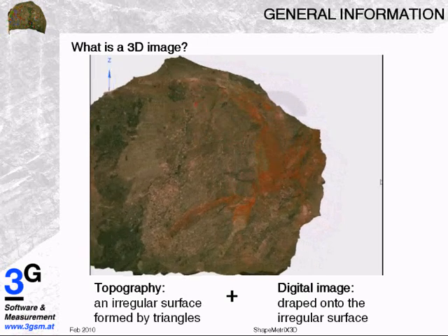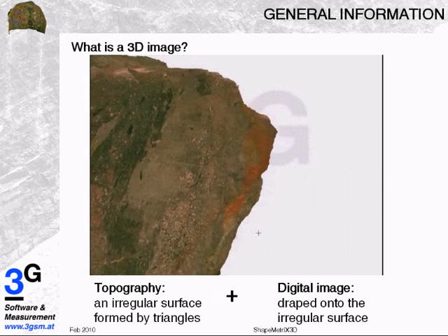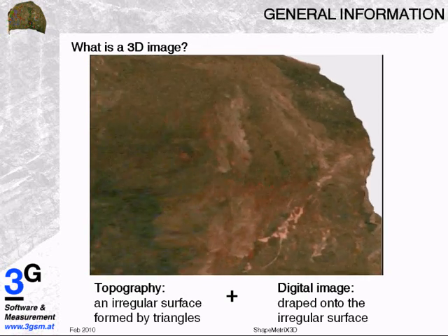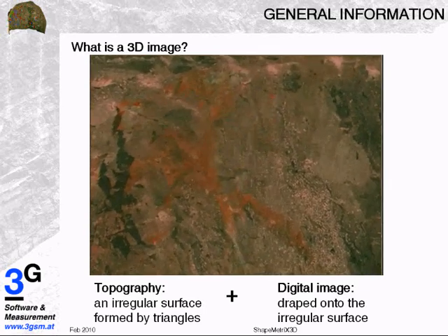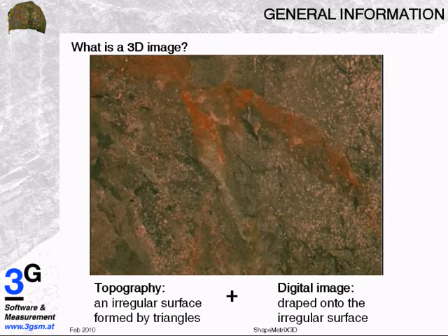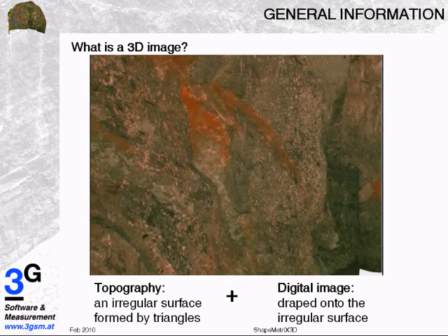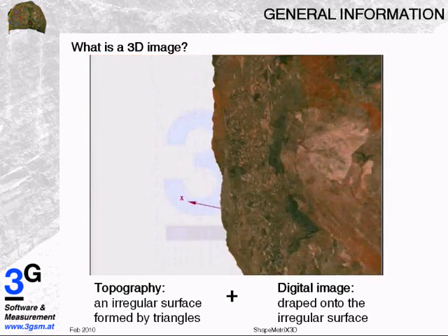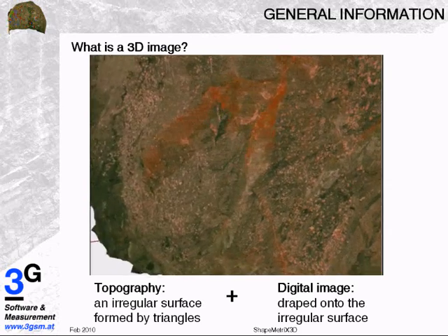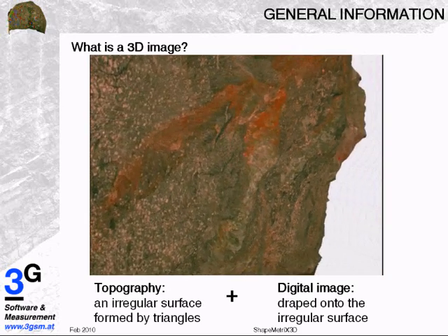The photograph and the mesh are always perfectly aligned, since all the measurements directly originate from the photographs. So this is a straightforward source when assessment of rock mass shall be performed.